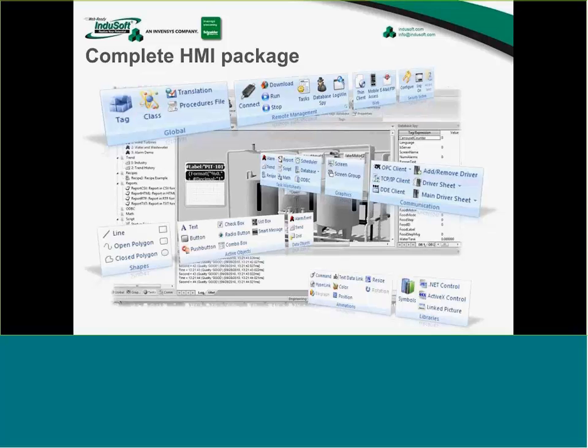I go through this screen really as a checklist for myself, but to show you really how complete it is. The product is based on tags, and so we have a tag database where you can define integers, Boolean, real, string, indirect addressing, arrays, pointers, lots of different ways to get at that.